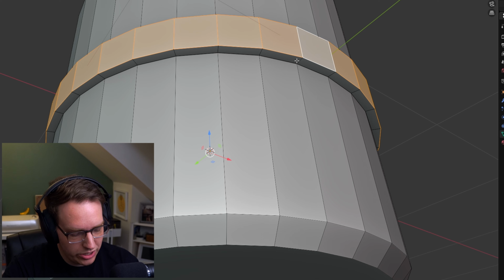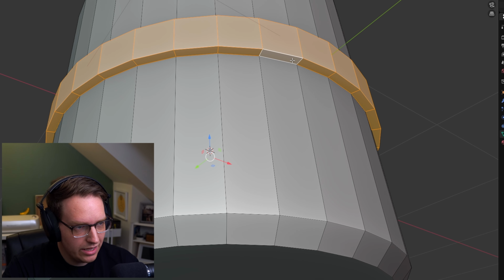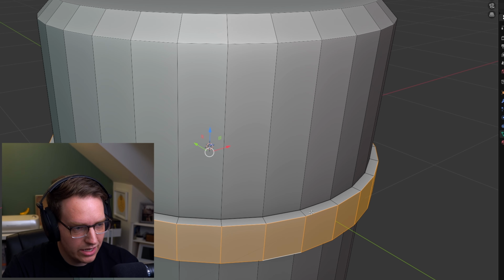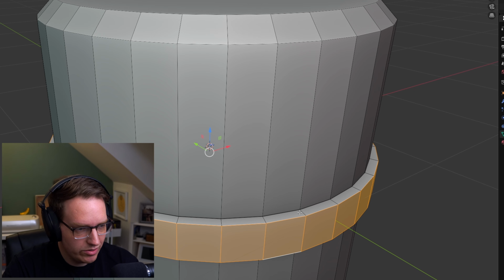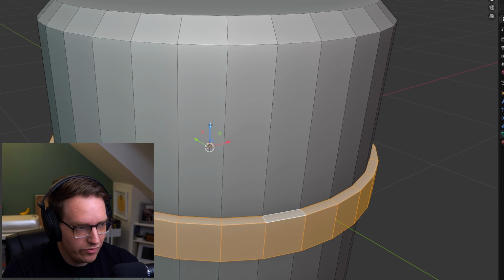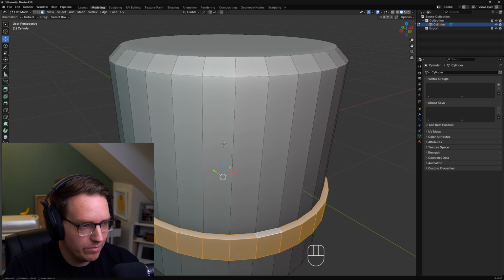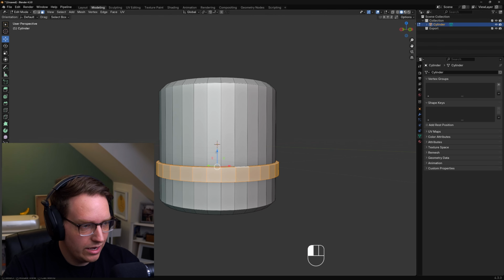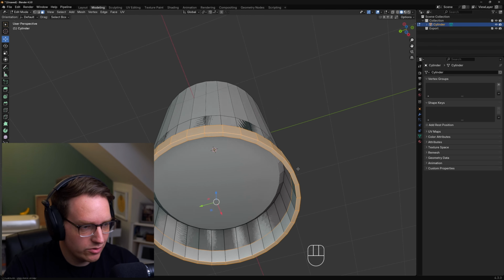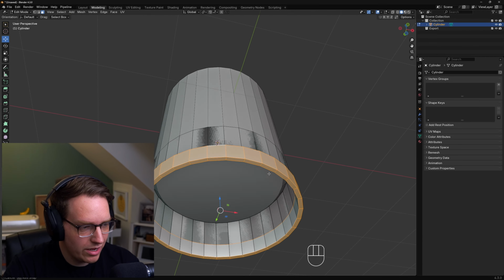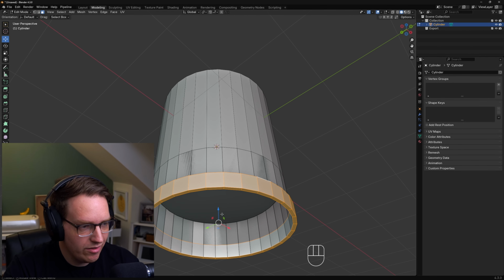So I'm going to hold down Shift and Alt, and I'm going to click on one of these bottom faces, and again, use the right mouse button clicking in to rotate. And now that I have all these faces selected, if I move, you'll see I can move the whole loop. All of them. I'm going to mouse wheel out. And if I pull off the bottom, I get this shimmery oddness. It's called non-manifold geometry. Don't worry about it right now. Anytime you see that, it's bad.